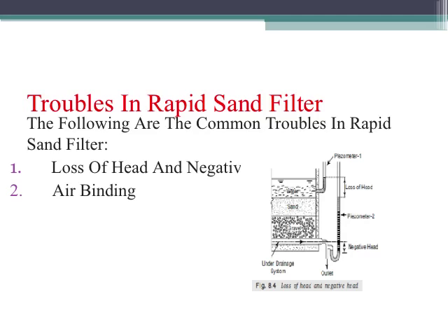This motion will be opposed by the resistance offered by the sand grains and the impurities that are arrested amongst them. The percolated water therefore loses some of its head, and the loss of head can be computed by knowing the water level in the filter and the pressure of water in the outlet pipe.